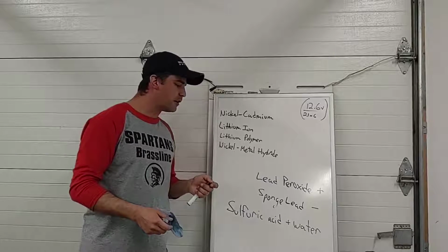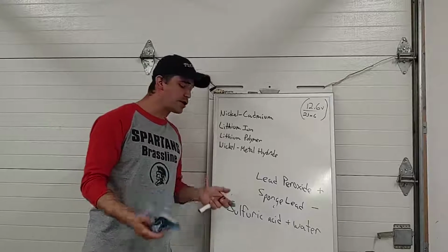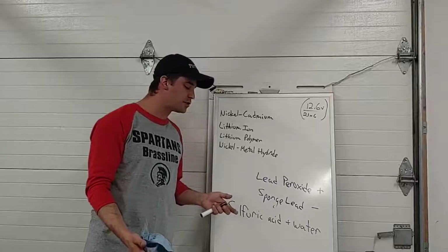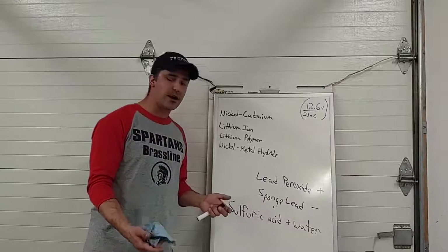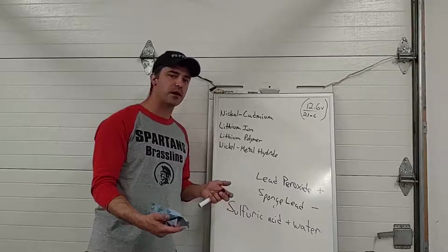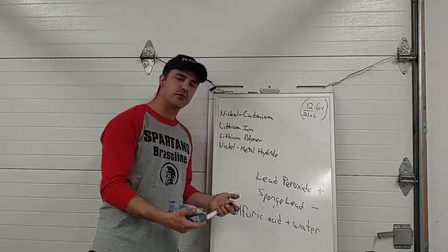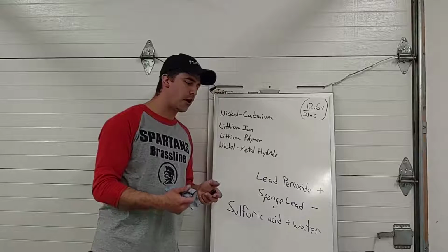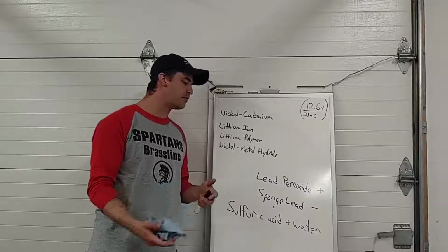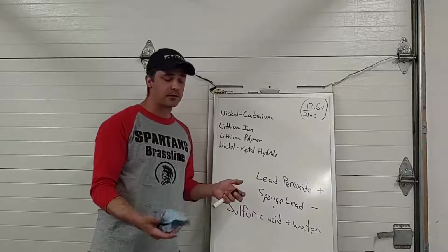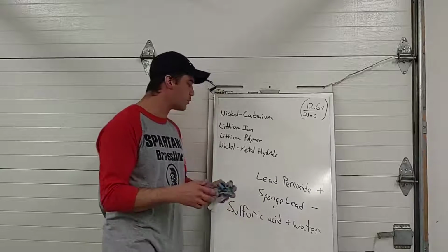They're going to have different characteristics as far as how they charge up and how quickly they discharge, so how long they can supply you with current, and exactly how they supply you with current. Some batteries are better at giving you a big surge of high current, but not for long periods of time, whereas other batteries are better at supplying you with a smaller current, but for longer periods of time. So we're going to talk about that as well.